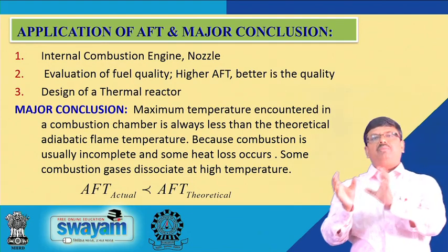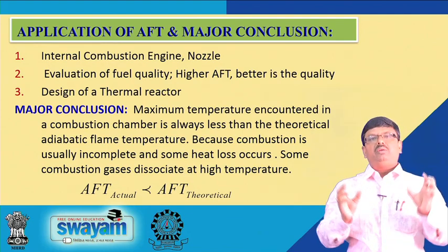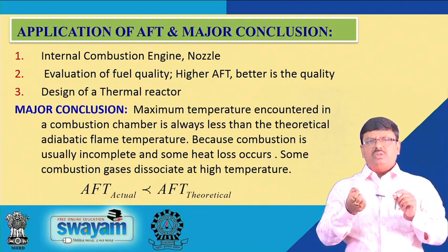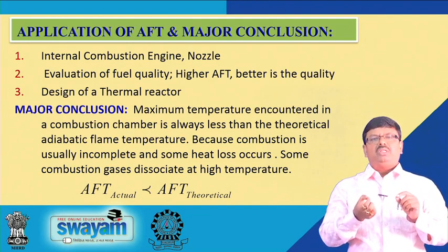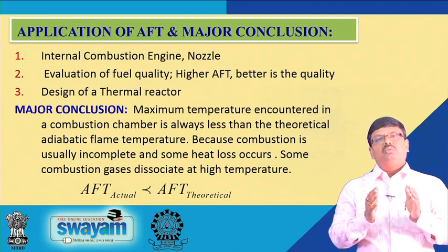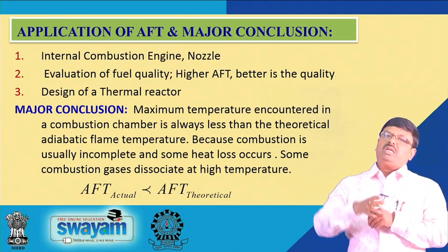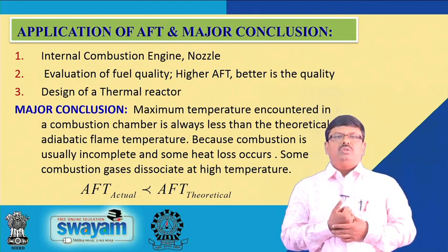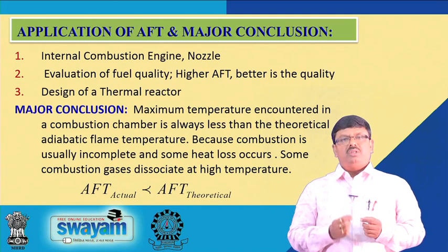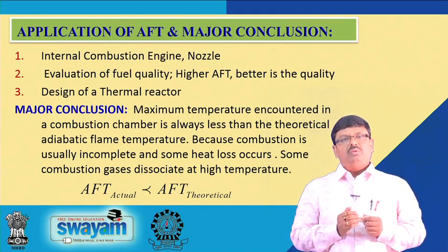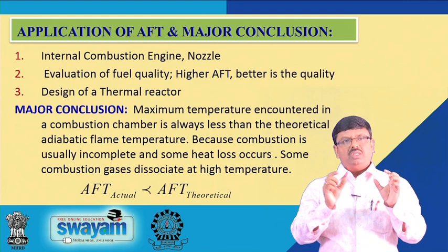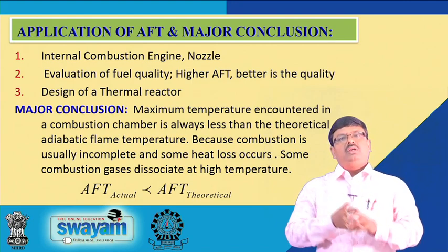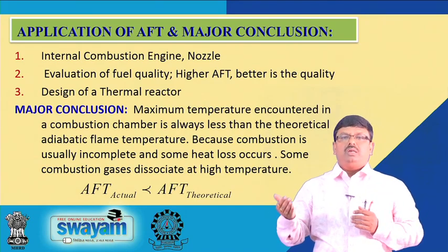Generally, in real practice it is not possible to achieve a 100% leak-proof system, so there might be chances of heat loss. If that is taken into account, the actual flame temperature will be less than the theoretical flame temperature. The second reason is the dissociation of the products, which is also one of the reasons the temperature may be lower. So, these are the 2 basic reasons why the temperature will always be less than the theoretical temperature.